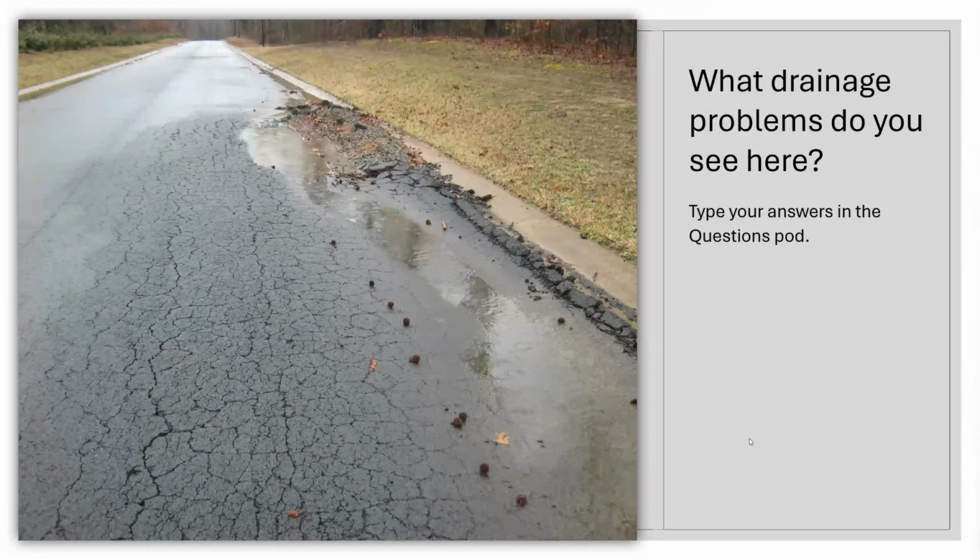I do see one other comment that came in about frozen water makes cracks. That's absolutely correct. Anytime you have a saturated pavement section, water freezes and expands. When it expands, it puts a lot of pressure inside that pavement and causes it to crack. So in addition to all the other reasons that we might have a cracking pavement, freezing water is going to make that 10 times worse. So all good comments.